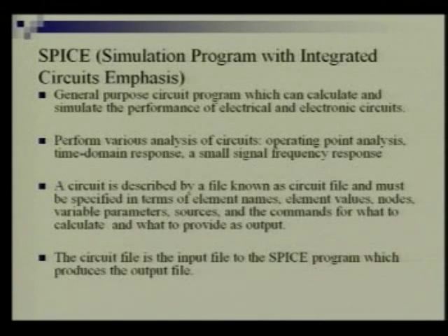And then it performs various analyses of circuits: operating point analysis, time domain response, small signal frequency response, everything it can do. As you can remember, when you did your analog circuit lab, suppose you are designing any small CE amplifier, what did you do in the beginning? The first thing you did? You did the DC analysis. So first you have to see whether the bias and all those things are perfect or not. Then you proceeded, you gave some signal, and then you saw how its frequency is responding and all that. So it has that capability, as if you are in a virtual lab, you can simulate the whole thing perfectly, okay?